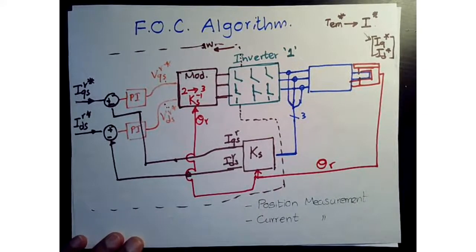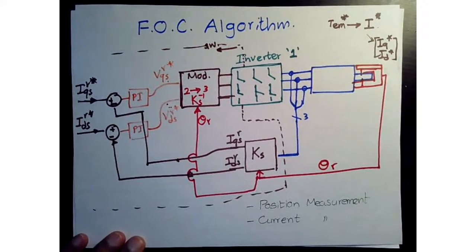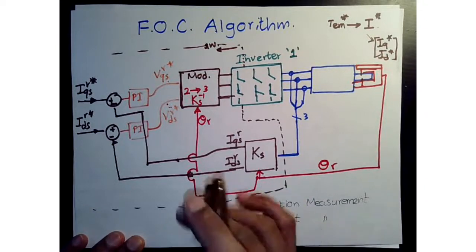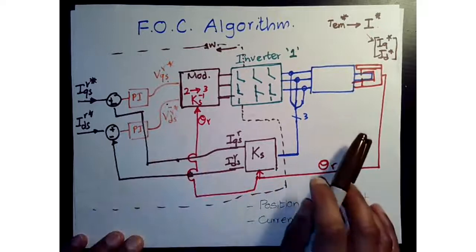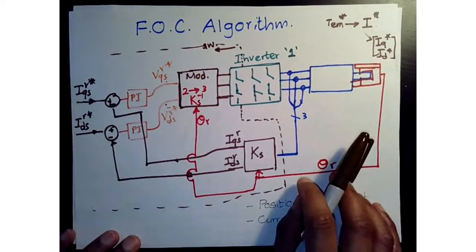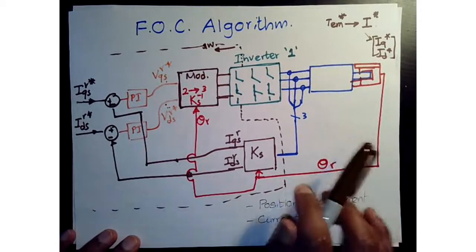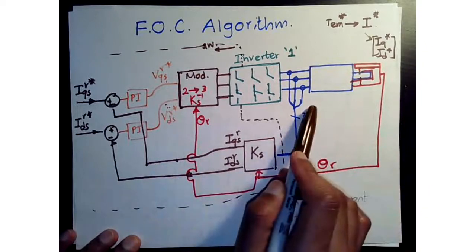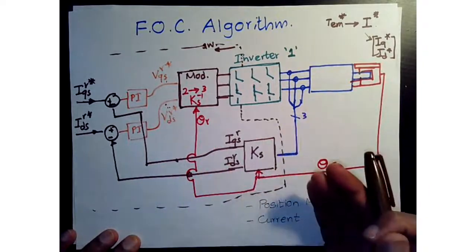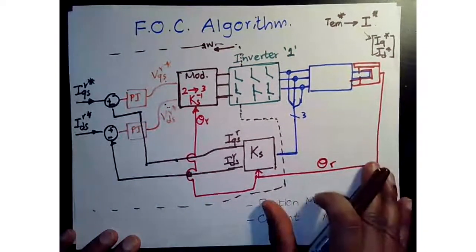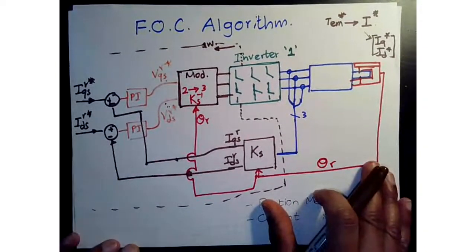Going into industry from academia, trying to learn these things in application, I saw that you don't need the differentiator, and I've tested with a differentiator, and it doesn't contribute that much in terms of performance, because sometimes it could make it worse because it'll amplify noise, and now your torque starts to vibrate and all that, so it might not perform well at all, right?